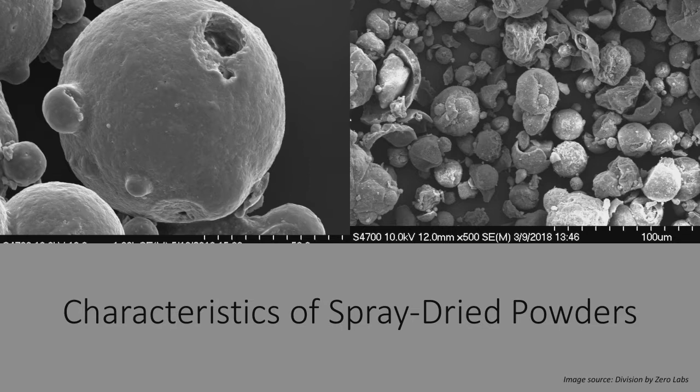This happens during that diffusion limited step, where the evaporated moisture has to escape this solid matrix one way or another. There's also a bunch of little pinholes that you can see. So sometimes that moisture bursts through and it creates a blowhole, and sometimes it starts to blow bubbles on the surface. This is a material that must have gone through an elastic state, as it must have been warmed enough that it had some elasticity, and the escaping gases could form bubbles like this.